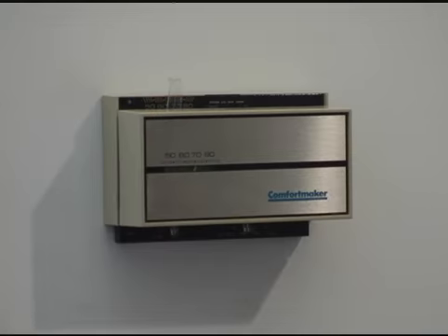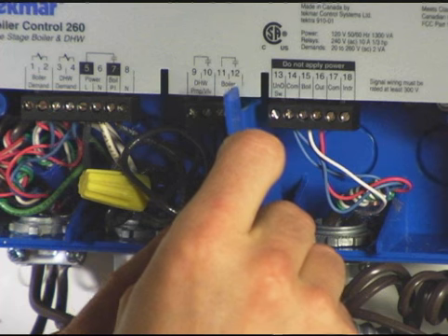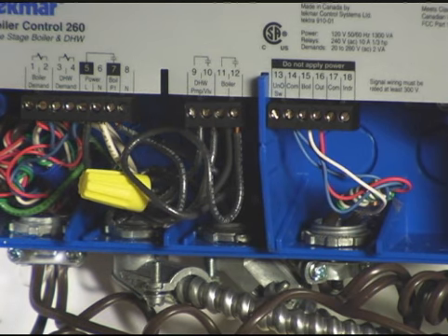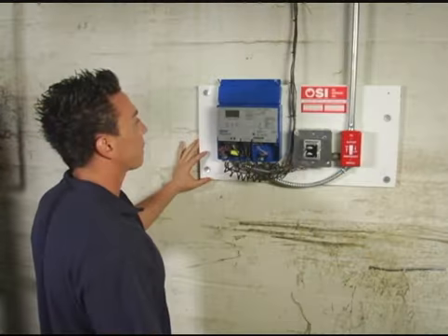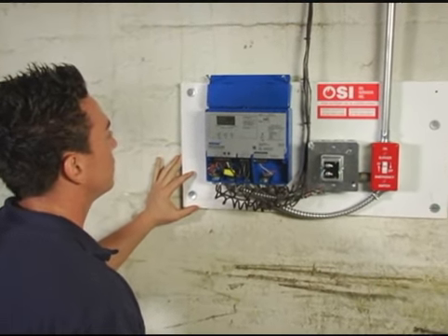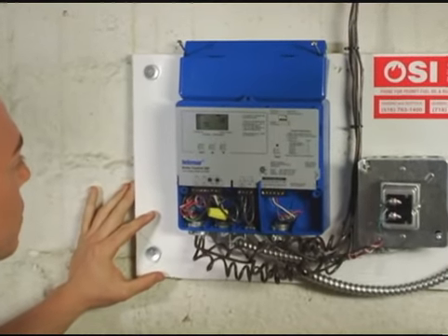Before applying power to the control, you should turn down all thermostats and the DHW aquastat to prevent a call for heat. Install the supplied safety divider between the unpowered sensor inputs and the powered wiring chambers. Apply power to the control. The operation of the control on power-up is described in the sequence of operation supplied by the manufacturer.